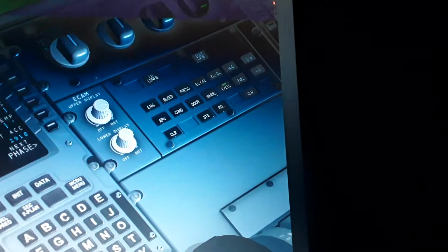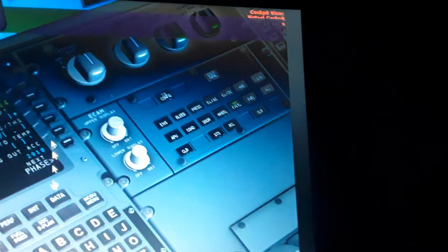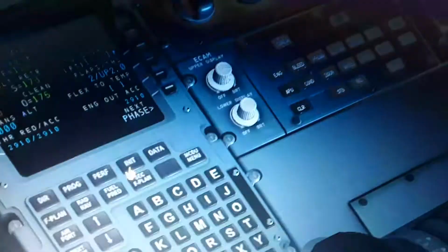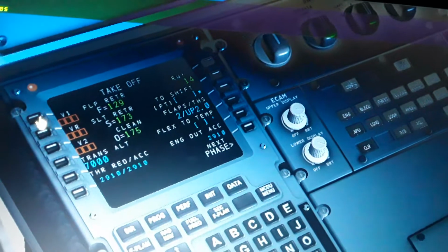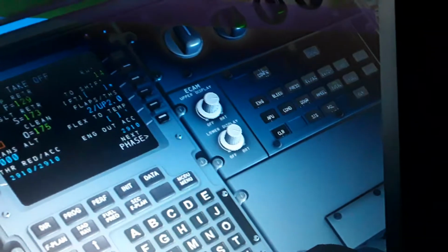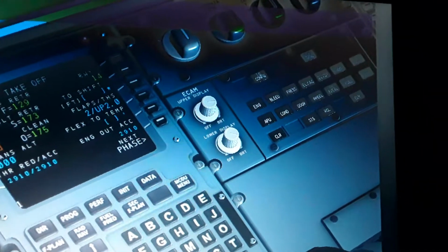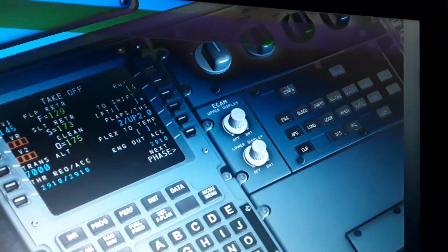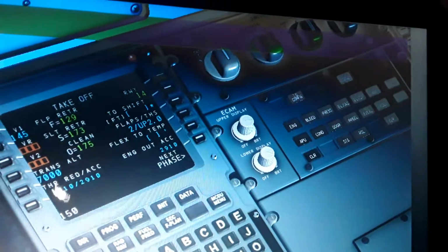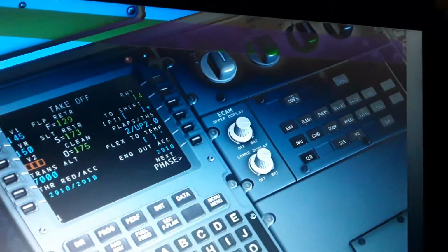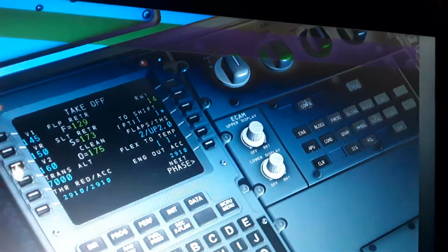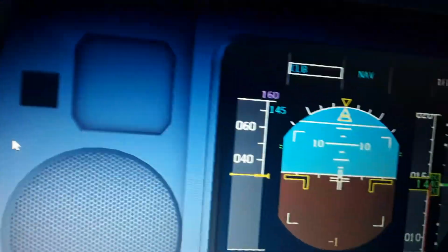So this is gonna be, with respect of the center of gravity, flaps 2, 20 up. It's gonna give us our V speeds, our takeoff speeds. I'm gonna use flaps 2 and we're ready to take off almost. The V speeds here, maybe I'm gonna set them on my own. 145, 150 and 160. This is a heavy aircraft, so we need a lot of airspeed.